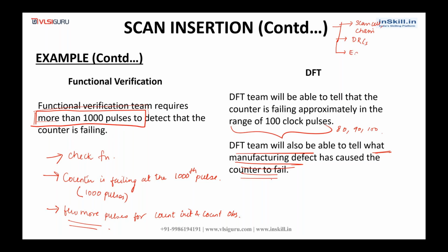And then edge mixing and domain mixing topics, scan chain balancing. Those things will be covered: edge mixing, domain mixing. That comes under the scan chain balancing topic. And then we'll give you an overview of scan chain reorder. Scan chain reorder will actually be done by the physical design team.